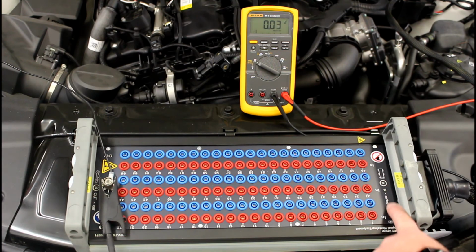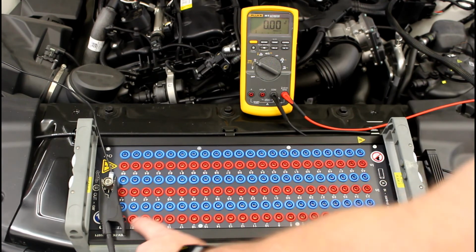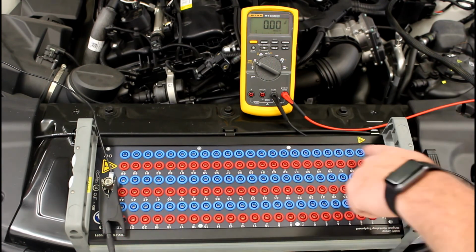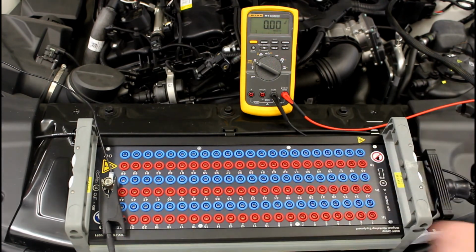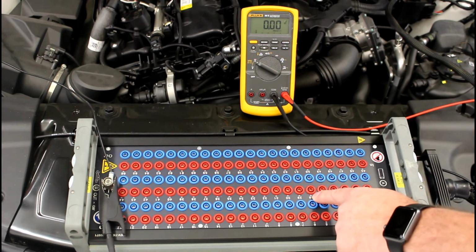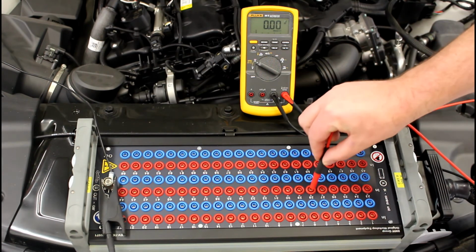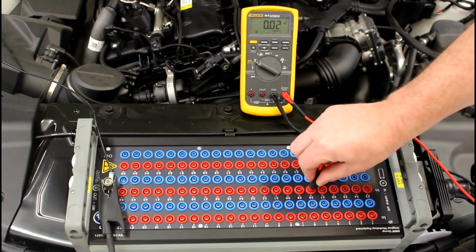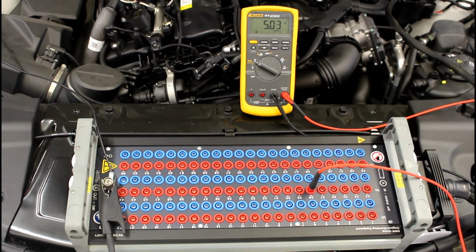Okay, so on A, the ECU side, we're going to use the red slots or terminals to check. And we're looking at number 28. So I'm just going to plug my multimeter in. We have 5 volts coming out of that ECU. Checking the ground will be easy now. That's terminal 38 as you see here on the diagram.